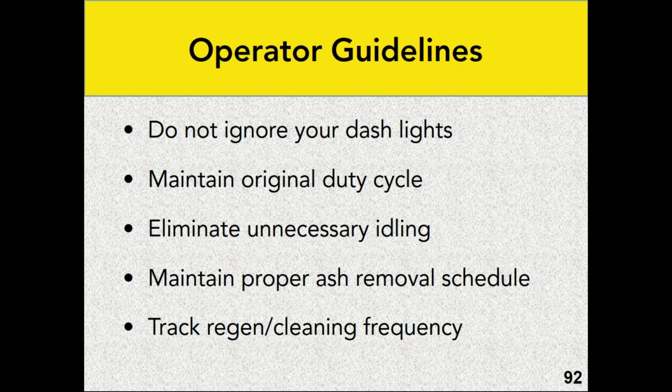If it's an OEM, you don't have to deal with that as much, but if you have a retrofit, you really seriously need to maintain the duty cycle as much as possible. Idling is a problem for all diesel particulate filters because it's always going to be a low temperature operation, which will have a tendency to produce more soot than the engine filtration system can remove.